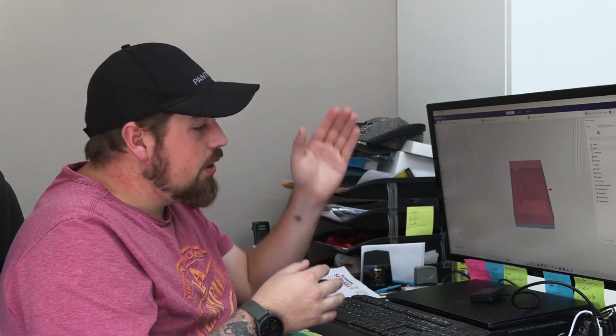So now that we have finished that and we've chosen where our two colors are going to be, I need you to go to the previous video where we showed you dual color and copy the settings that you need for your purge tower, which is all here on the right hand side. Once you've copied those settings and you've done it to the T, you can go ahead and slice your model, download it onto the memory stick, and we can go straight to the printer.